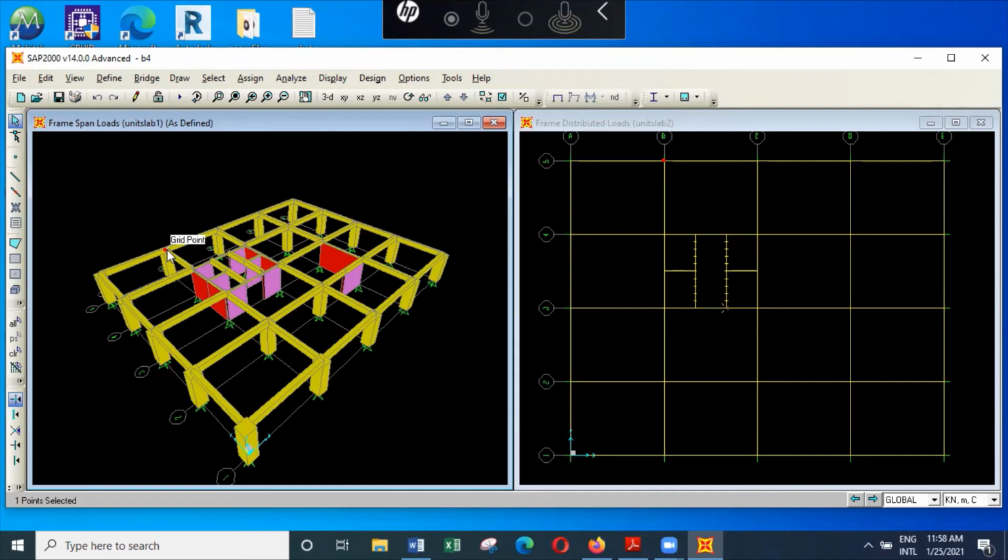So you can have a number of mode shapes, and generally you will find the first 3 to 4 mode shapes will be dominant, whereas the other mode shapes will not dominate. So to determine the dynamic properties, you need to have the correct mass of the structure. Correct mass of the structure.